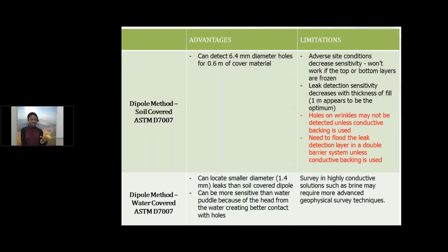A limitation is if the water is saline, then the conductivity gets too high, and it may be a little bit complicated for just the normal dipole method, and other advanced testing may be required.